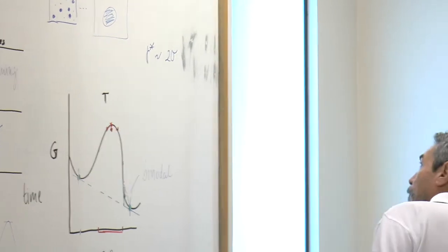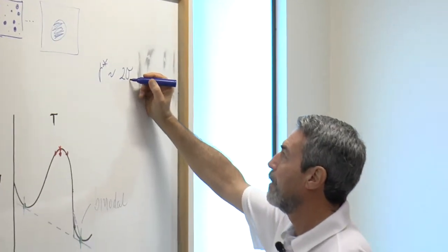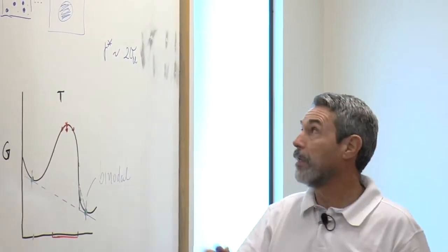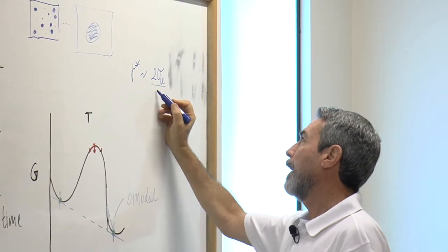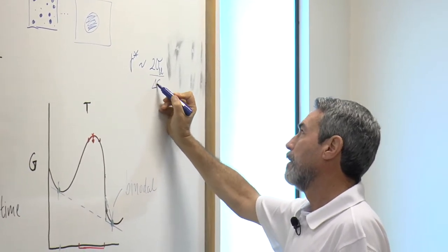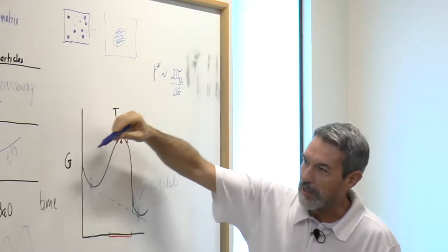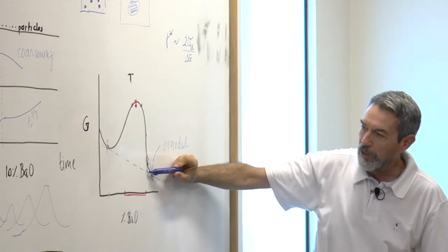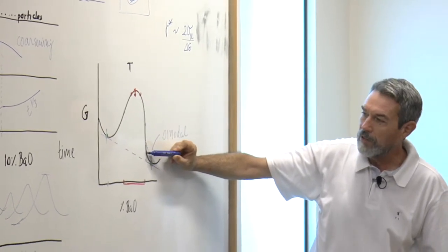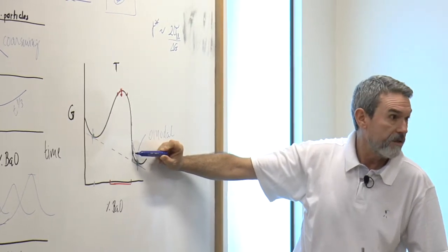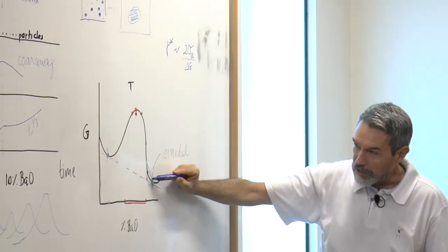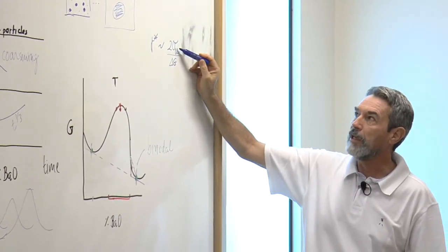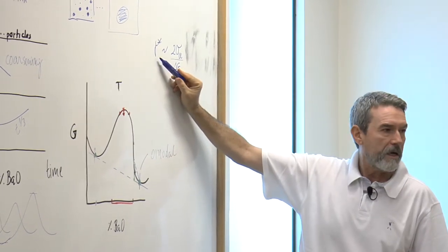In this case, it will be the surface energy of one liquid inside the other liquid, divided by the delta G. And the delta G is exactly this, the free energy of the separated system minus the free energy of the single phase system. So we know delta G. If we know delta G and the surface energy, it determines a critical radius.